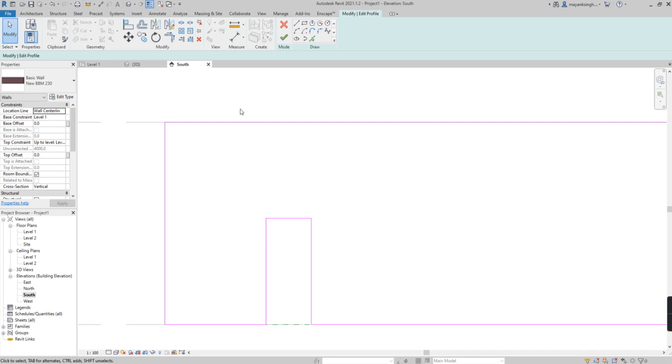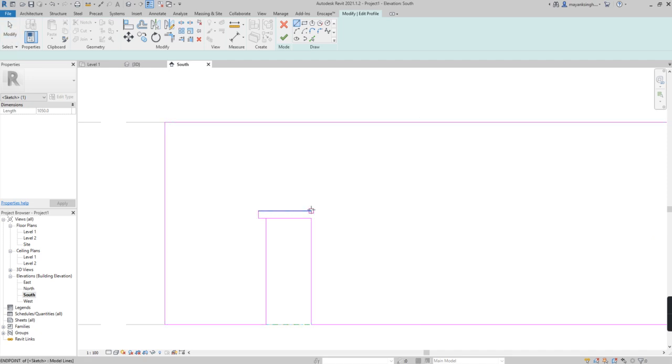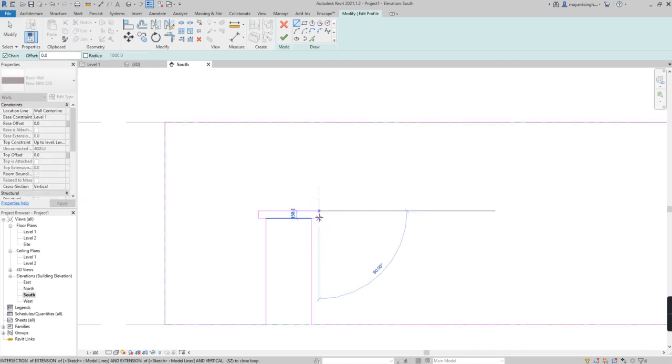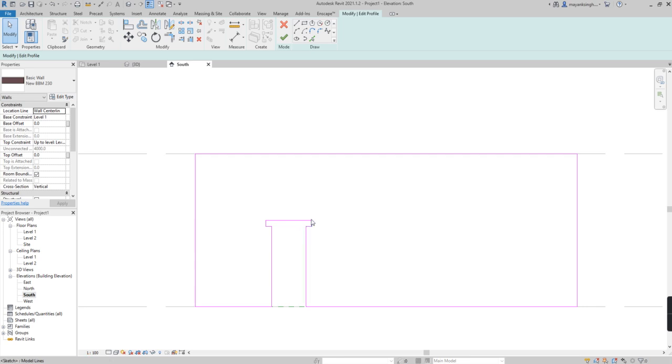That's since we have to detail out this plate for a door, even the lintel has to be visible. So I'm going to make another line, which is 150, snaps straight x-axis, straight y-axis, another 150. Then I go till here, end, and then take 150, another one here. Then another 150 on the right, then down, and then here, and then I can delete this. So this is this part where I can make a lintel, and here we're going to have a door. So I'm done with the modeling of the wall.